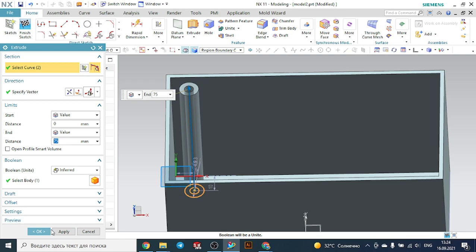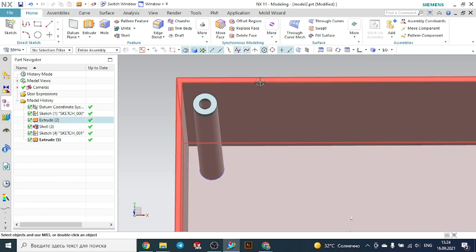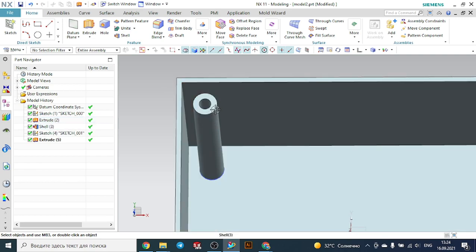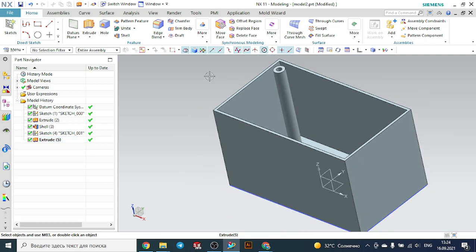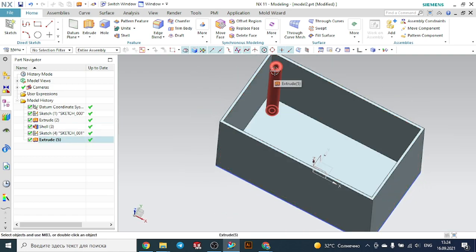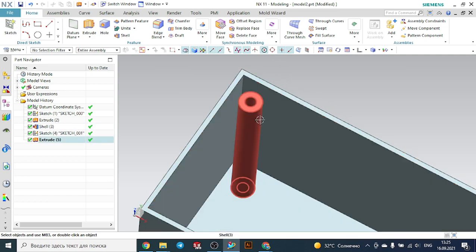In the case of plastic materials, if I have such kind of system and such kind of wall, in order to support this one, the plastic material is too weak. So the rib is used in order to support this system, in order to increase the force restrictions or so on. I want to make the rib for such kind of system to give strength to this kind of element. Since it is plastic material, it will be too weak. So I want to make some support. So in this case, I will use the rib.